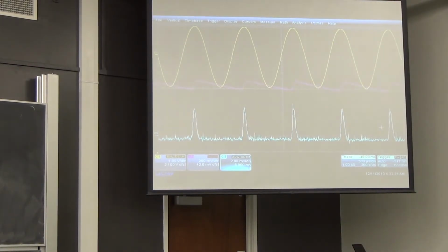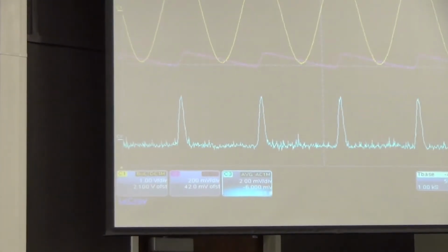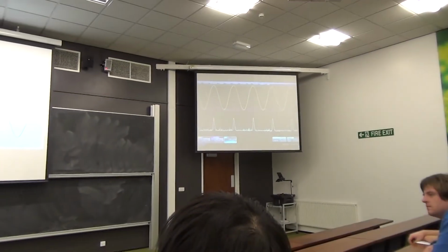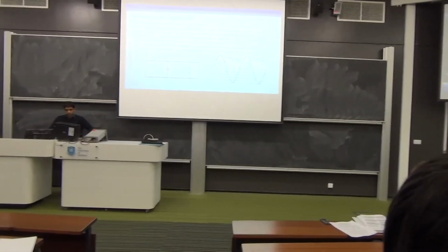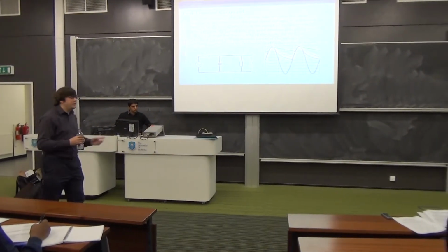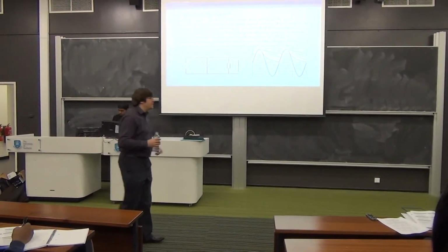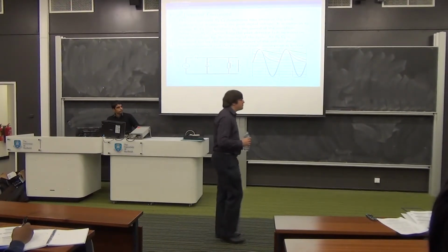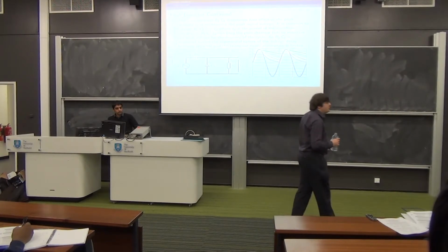The important thing here is that the amount of charge being transferred is getting squished up in time, which is why the current has to be bigger. You've got to get a certain amount of charge in, and you've only got a certain amount of time when the diode is conducting, so it must conduct a higher current in that part of the waveform.